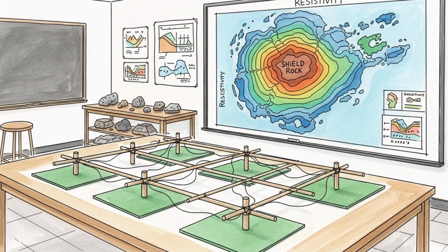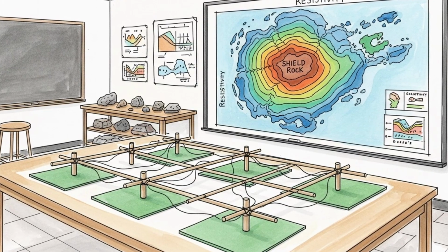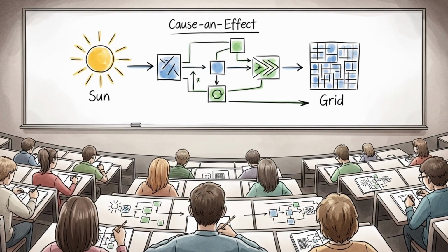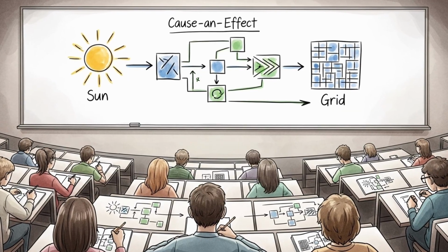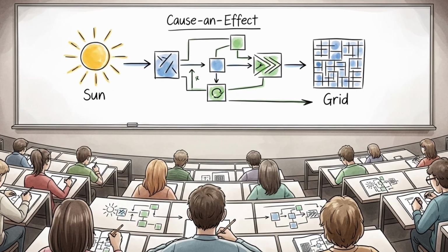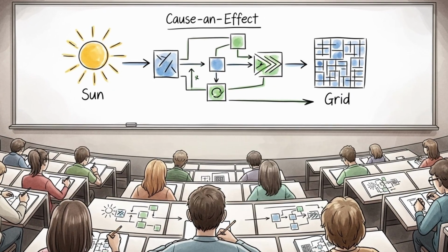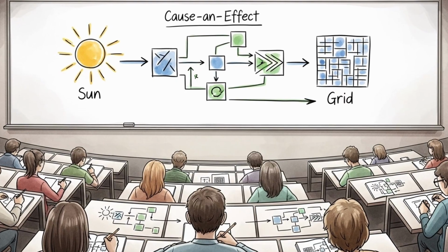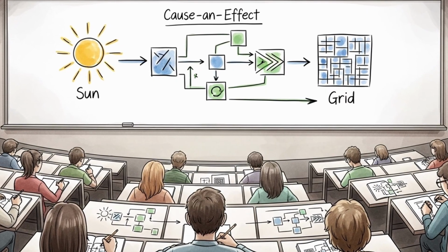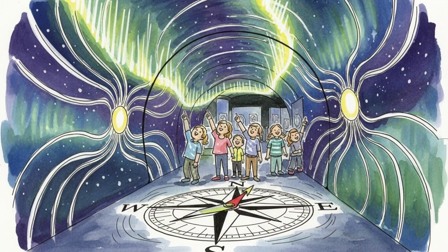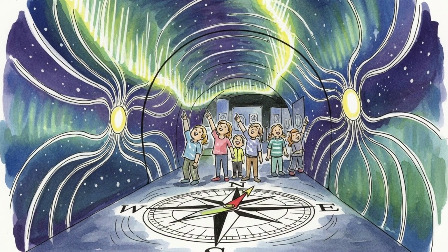The second is to fly at lower altitudes than planned. The third is to delay departure. Each option has a fuel and time cost. The decision uses simple inputs: event level, expected duration along the route, and available diversion airports. Policies define threshold for action and for crew composition, including rules that apply to pregnant crew members.